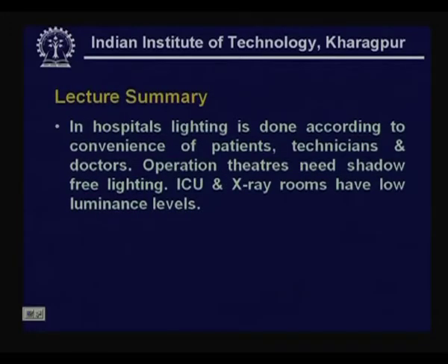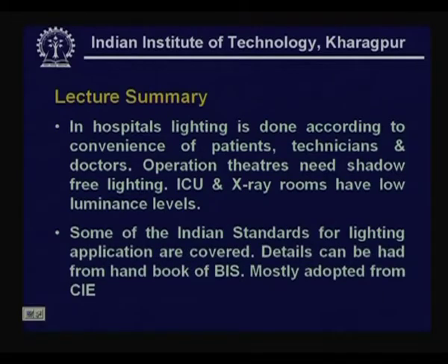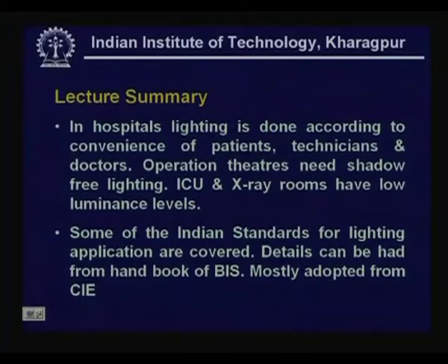In hospitals, lighting is done according to the convenience of patients, technicians and doctors. Operation theatres need shadow-free lighting. ICU and X-ray rooms have very low illuminance levels, and some of the Indian standards for lighting applications have been mentioned in this lecture. Details can be had from the handbook of BIS, and these are mostly adapted from CIE.